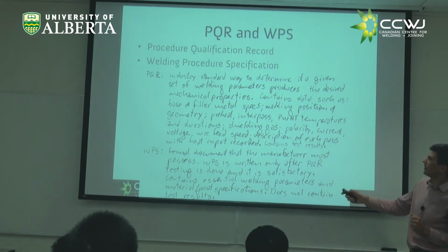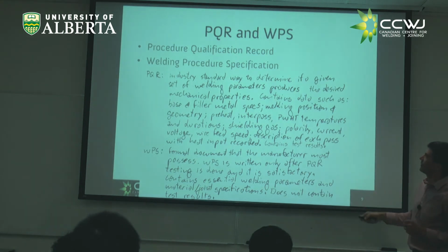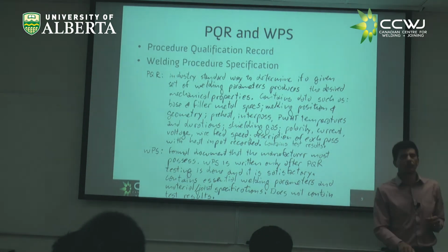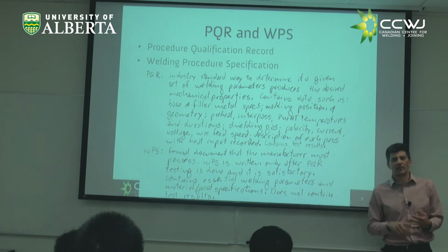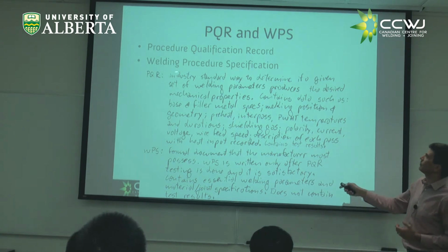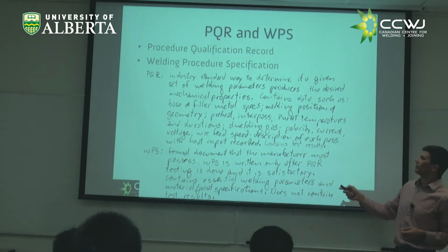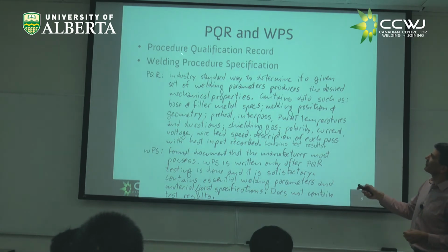So the music sheet is a welding procedure specification that says, what should you do? How many volts? How many amps? What velocity? What electrode? All this. This is a welding procedure specification, and it's called WPS. And there is something else that comes before.